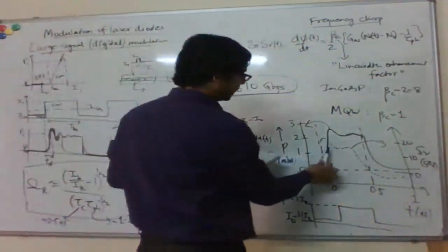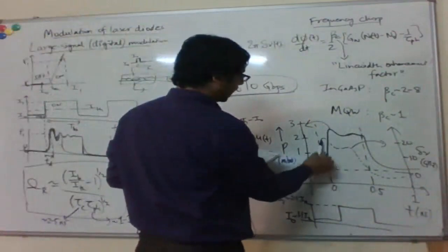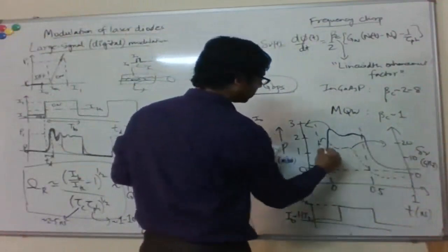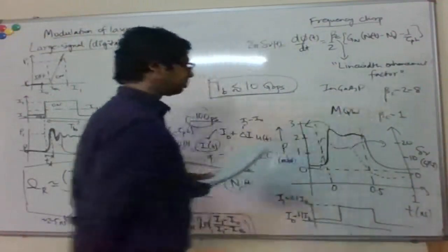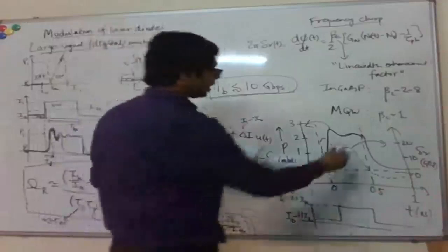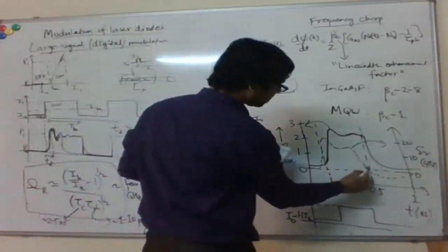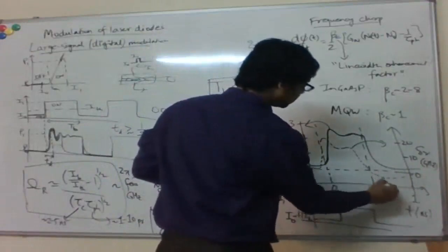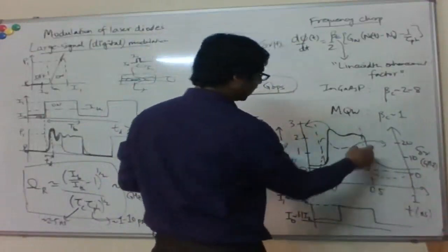Okay, so you can see basically as the optical power is rising, near the leading edge of the pulse, this delta nu is positive, or a blue shift. And then near the trailing edge of the pulse, this decreases and even goes negative, below 0, like a red shift near the trailing edge of the pulse.